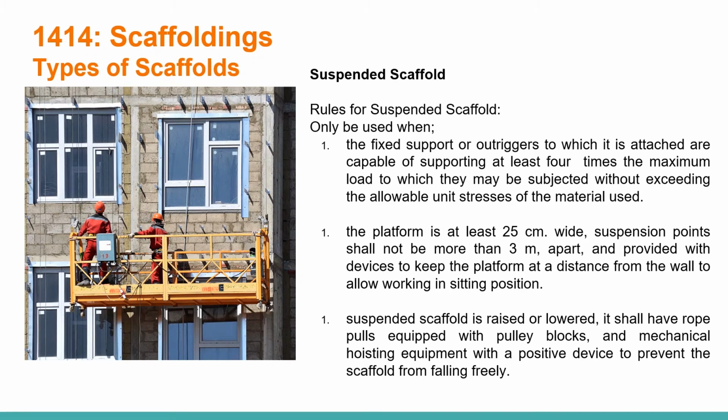If a suspended scaffold is raised or lowered, it shall have rope pulls equipped with pulley blocks and mechanical hoisting equipment with a positive device to prevent the scaffold from falling through.